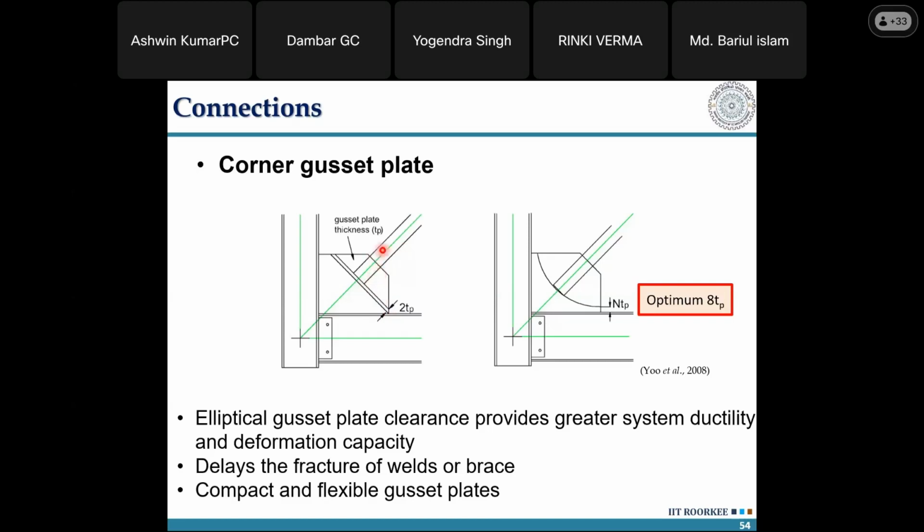So let's say I idealize that I cut a slit in the brace throughout the top and the bottom plate, and then insert my gusset plate, which means I have 4 faces for welding the gusset plate to the brace. So I do fillet welding, let's say, and I consider 0.707 multiplied by the thickness of the weld multiplied by the allowable yield stress of the weld or the stress in the base metal, whichever is lower, and then the length of the weld that I take is such that it is equal to the maximum capacity of the brace.